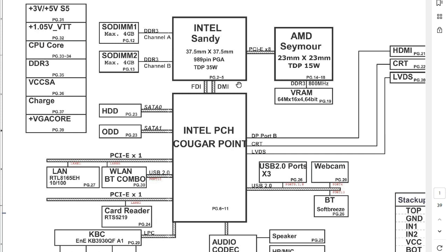If you focus here, you will see in this block diagram that we have just two chipsets: the CPU and the PCH. In any motherboard, you should normally find four chipsets: the CPU, the North Bridge, the graphic card, and the ICH. The PCH here integrates three chipsets: the North Bridge, the ICH, and the graphic card. That's why we call it PCH.